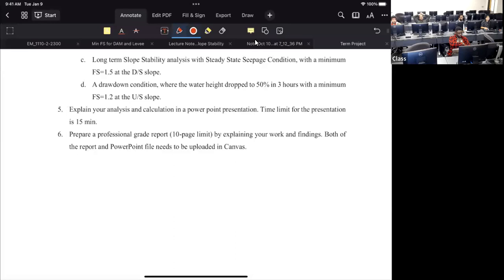What change has been made? Return period analysis, considering a newer kind of frequency or return period during design. For example, if it was 100 years, now they are considering 500 years. Thinking about it, or has the change been made? The change has already been made.